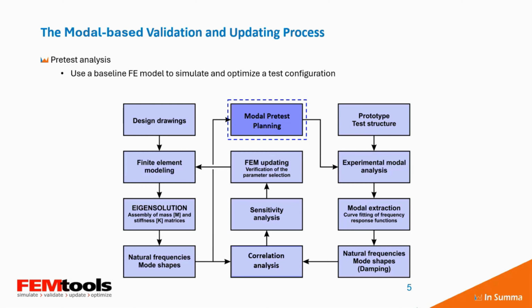In this slide, we show the modal-based process. This baseline FE model can really be useful to help the test engineers to define the test setup in terms of the sensor locations, excitation, shaker locations, support locations, and so on.